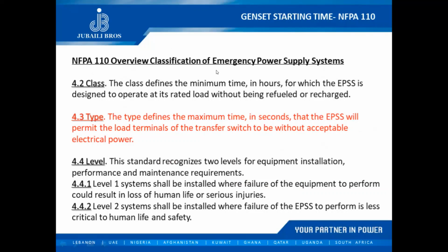If a consultant comes around and tells you, I need the genset to be ready in 10 seconds, or I need the genset to comply with NFPA 110 type 10, you can simply answer that NFPA 110 is not strictly related to the genset, it's related to the entire emergency system. There's NFPA 110 class, there's NFPA 110 type, and there's NFPA 110 level.